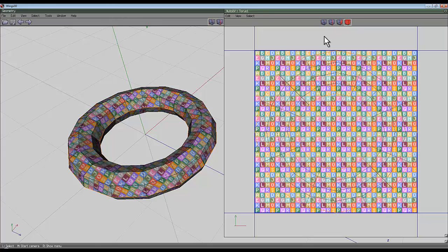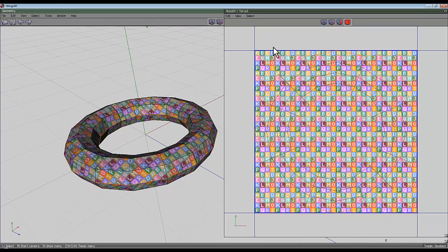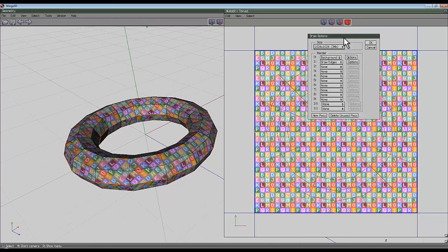At this point we haven't got a texture for this face. This is just like a preview mode. But if we right click, we can create a texture, and you have some options here. So in the background option, well, resolution's fairly easy, you should be able to work that out, but in the background option, if we go to options here, you can have image or color. Now if you have image, you can have this AUVBG, and that's this pattern, which is quite handy for judging the scaling. But for a template, you might want to use color, select color as white, and have draw edges, and just draw the edges.